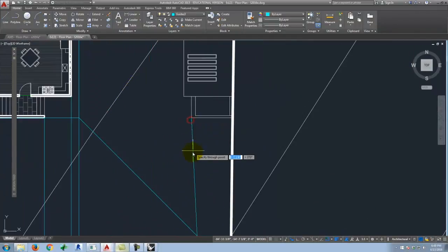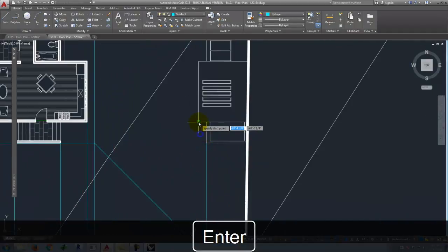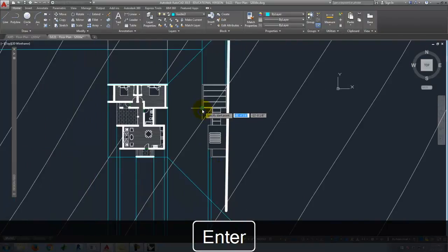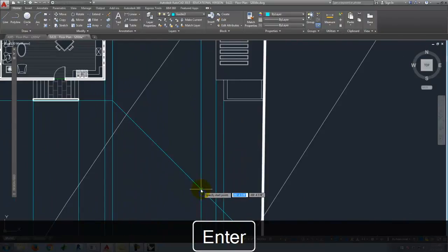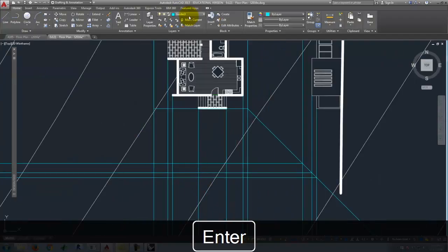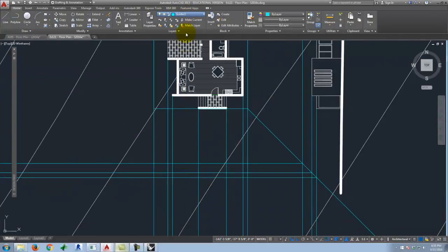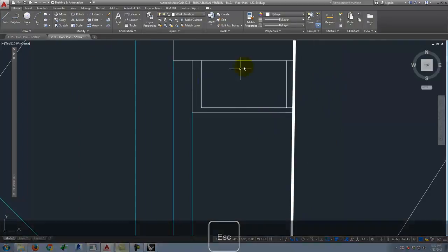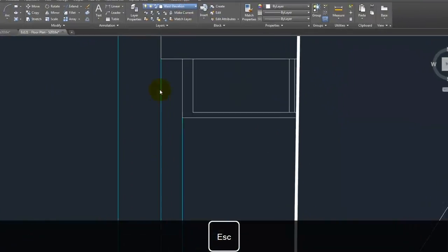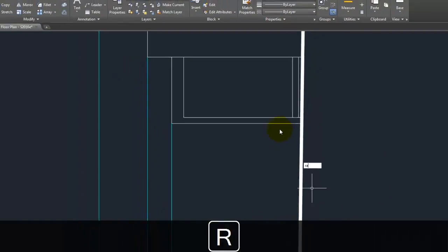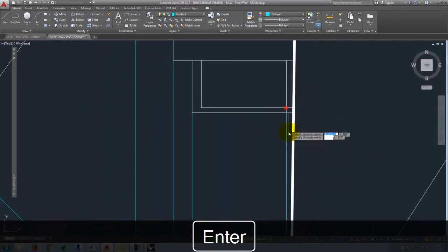So we can pull across a height. Let me turn back on ortho mode here. For that, for this, and for this. And I can then pull these across there, there, and there. Okay, so now we'll turn back on my west elevation, if I can find it. There we go. And we'll go ahead and start to draw. Oh, I need the base. I need the base here. One more. Back on my guides. And we'll go again at my floor level.